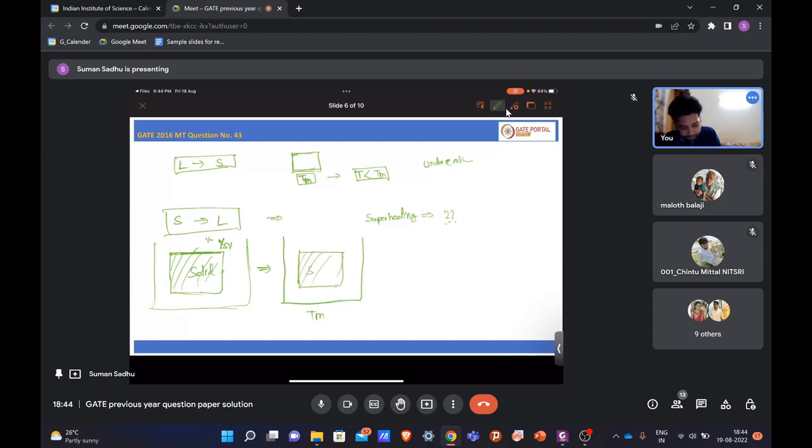So this is solid and there is also a liquid layer formed, right? For the liquid layer, it will create a liquid-vapor interface with energy gamma LV, and another interface, the solid-liquid interface, which will also have some energy, gamma SL. So basically you are breaking the gamma SV interface, and you are creating two new interfaces, gamma LV and gamma SL.